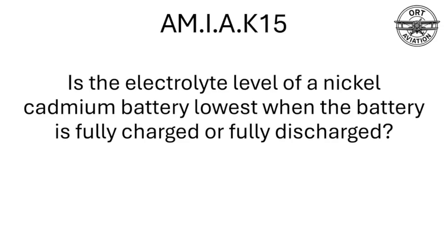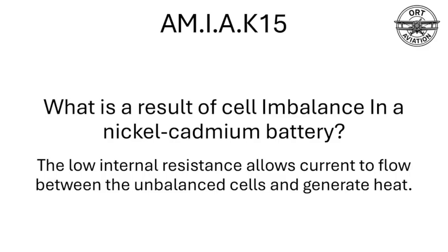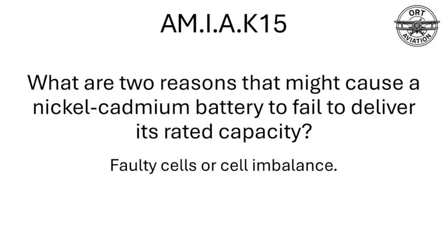Is the electrolyte level of a nickel-cadmium battery lowest when the battery is fully charged or fully discharged? Fully discharged. What is the result of a cell imbalance in a nickel-cadmium battery? The low internal resistance allows current to flow between the unbalanced cells and generate heat. What are two reasons that might cause a nickel-cadmium battery to fail to deliver its rated capacity? Faulty cells or cell imbalance.